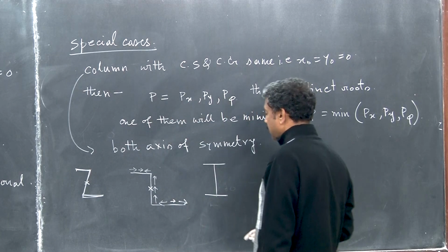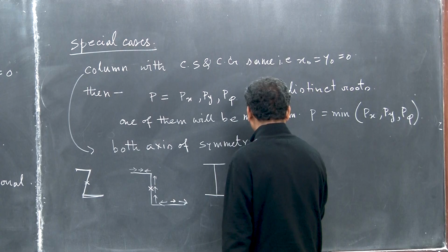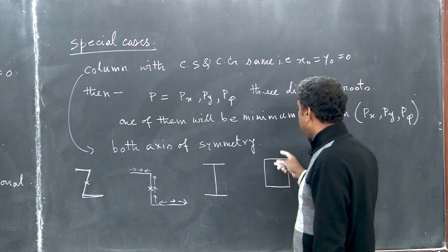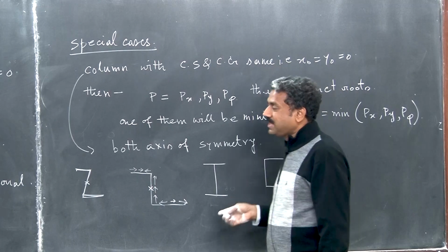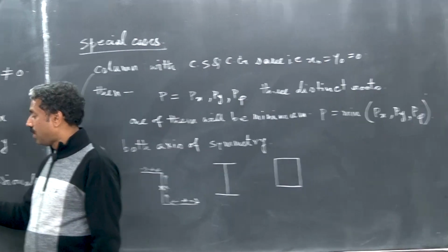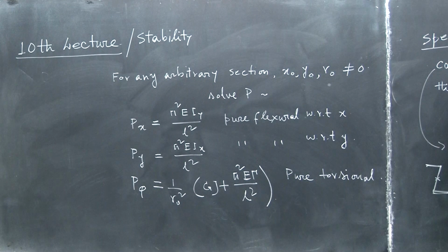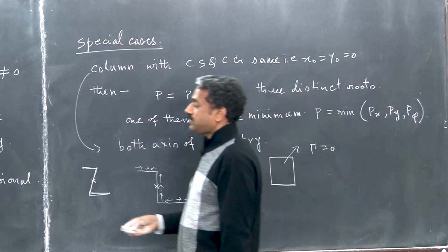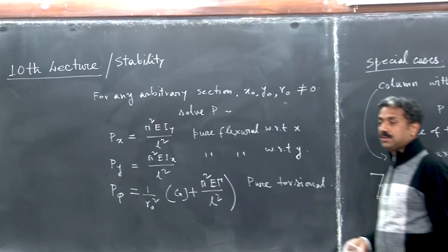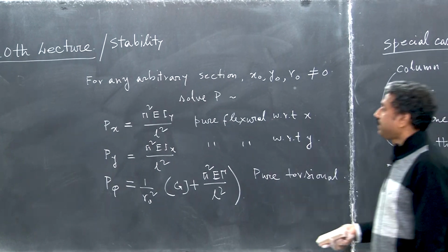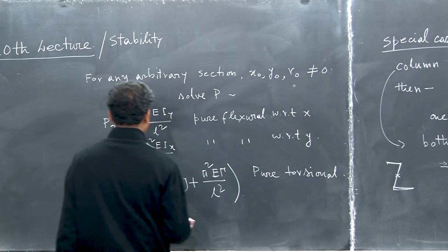And then of course, if you want to consider this rectangular section, a closed section, then warping is very negligible. So the warping constant, capital omega, becomes 0 for this kind of section, and then this term will not be there, okay. This is very low warping.